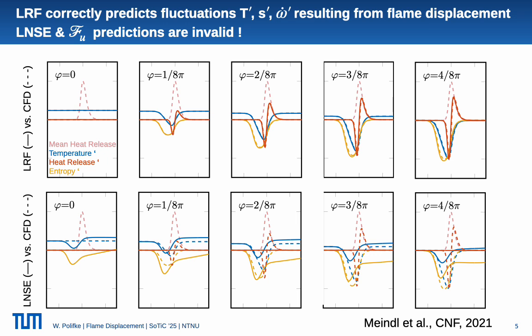The temperature also shows an overall decrease with the isentropic response to pressure changes. What is really worrisome is the entropy wave, or the field of entropy fluctuations, which very clearly shows fluctuation of entropy at the exit of the domain. That is, our linearized Navier-Stokes, in this case, generates an entropy wave where it shouldn't, because this is an ideal premixed flame as introduced previously.